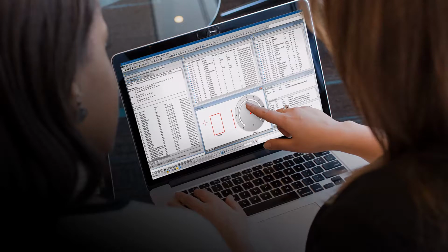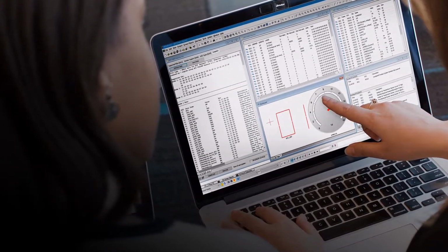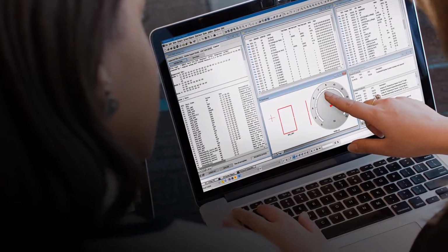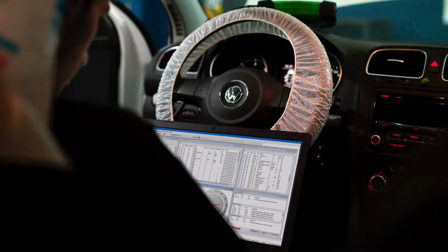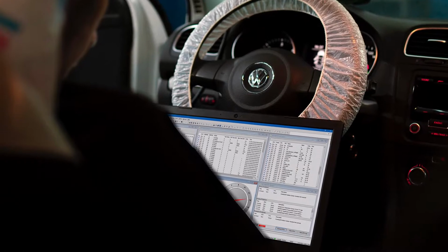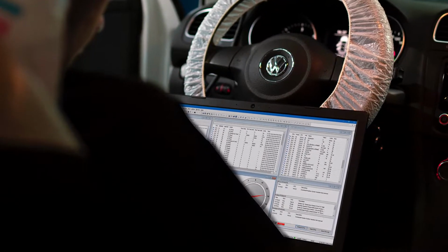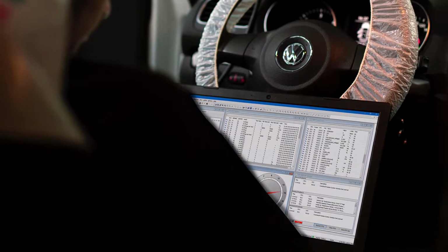These services control what access the connected tool has to the ECU functions and data. For example, flash programming through UDS is restricted to end users with correct security access. This would be limited to OEM-approved parties or tools. The exact security and session setups in vehicle are dictated by the ECU supplier and OEM specification.